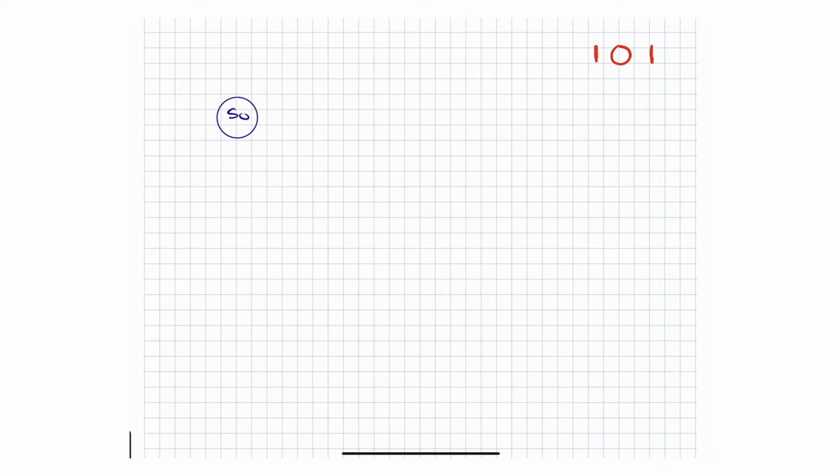And I haven't seen anything. Sometimes you can see some books or online websites will show you this arrow, meaning whenever you press reset, we're going to go back in here. All right, so now if the input is 0, it's not part of the sequence I'm looking for, so I'm going to just stay in that reset state. I'm going to say 0, and I'm just going to write that the output will be 0 as well because I haven't seen the sequence yet.